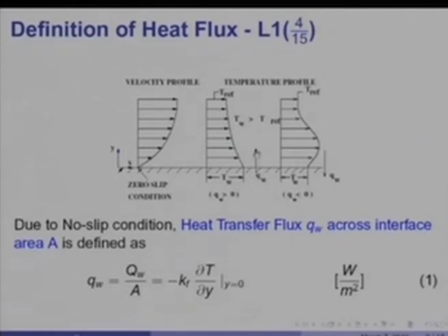If there was a heat transfer, then the most commonly developed temperature profile will be as shown in this, where there would be some reference temperature far away from the wall and the wall temperature would be greater than fluid temperature. So, the heat transfer would take place that way.